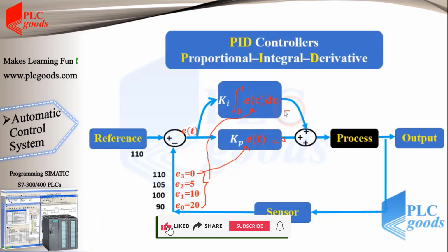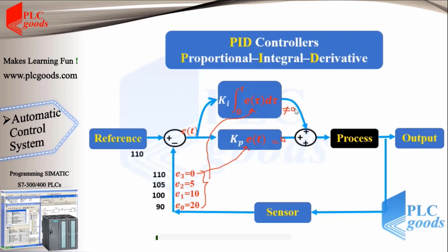This feature can help to keep the water level at the desired SP value, but it has a weakness in the beginning. The previous error values are larger numbers, and when the integral term sums them to determine its output, it will generate a large output value to open the inlet valve as well.